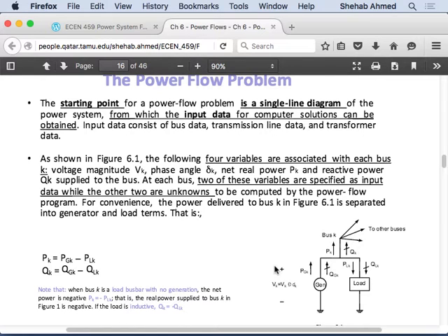So at these buses with these generators that will be providing this fluctuating power, I will use them as a reference for voltage and angle, right? And these buses will be called slack buses or swing buses. Swing meaning they swing the power, right? So they're called slack or swing buses. You will typically have one or more slack or swing buses in the system, and that is what you actually need to solve the equations. But this is actually physically present as well, right?